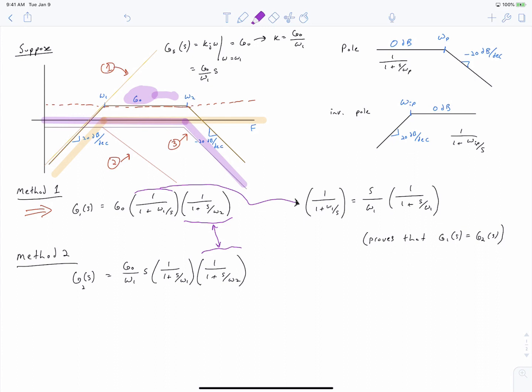to navigate both to higher frequencies, which is relatively easy with poles and zeros, because a pole and a zero always starts at 0 decibels and then goes to something else. So that was simple enough. But we also had to navigate towards lower frequencies, and that's where things got complicated. Regular poles and zeros don't end at 0 decibels, they begin at 0 decibels, and so we had to do this calculation up here in order to normalize our transfer function, in order to figure out what the DC gain or the constant gain should be of our transfer function. And that's where things got a little bit complicated. Not impossible, but a bit complicated.